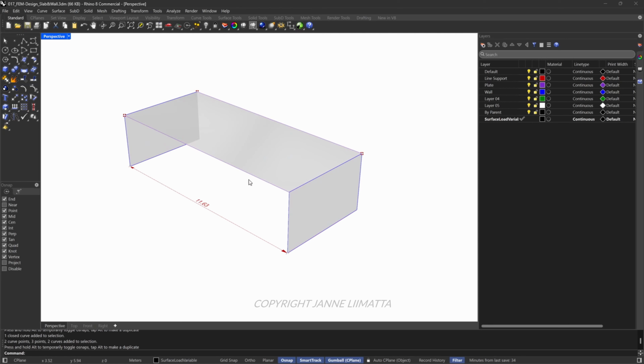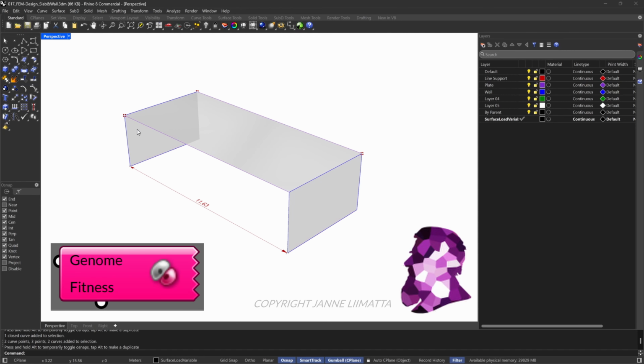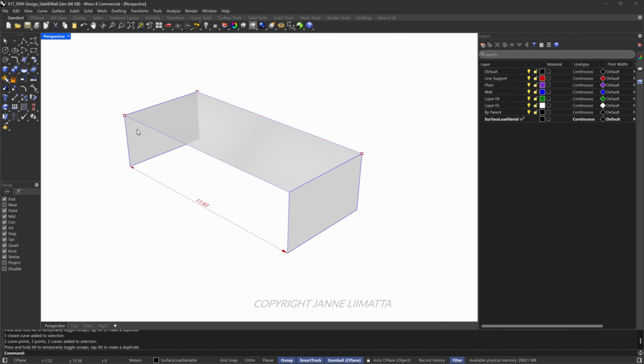Let's imagine that I want to add another wall under the slab, and I want to optimize it to minimize deflections. I can either perform an iterative analysis, or I can create a load of variations of this model and then choose the one that has the best performance. The first one we can perform with Grasshopper by using iterative solvers like Galapagos or Wallace, but we will first try the second option. The upside of that is that you can visually see all the variations next to each other.